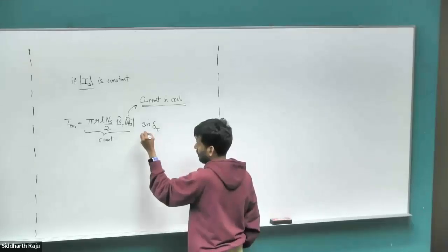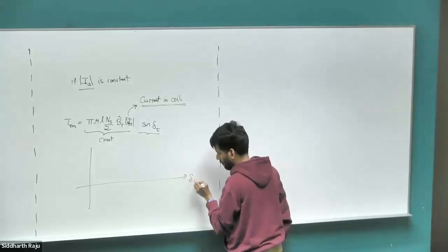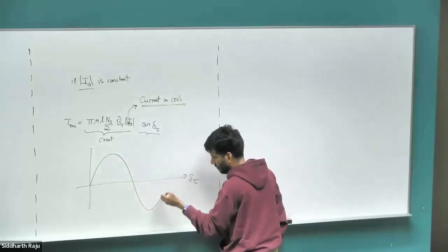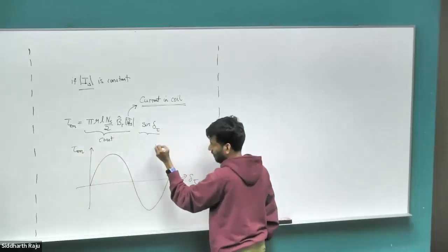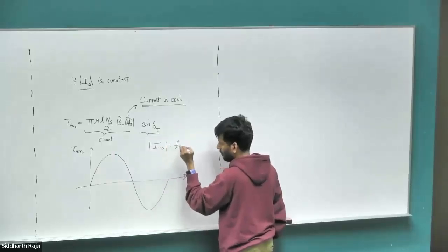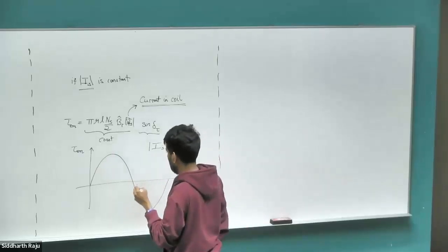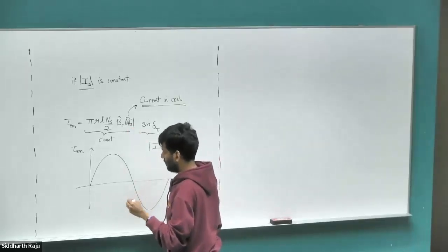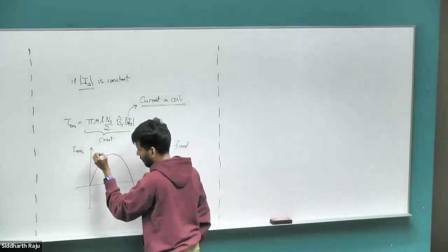So given all of these are constant, this is the only term that varies, and we can plot that as a function of the torque angle delta tau, and then the torque that is generated tau em. So again, this is very important. I magnitude is fixed. If that is not the case, then a whole other set of equations come about, which we will see, which will describe the power angle. But this is the case where the drive maintains a constant current. And when that is the case, depending on where the load torque is, let's say this peak is some 5 Newton meter.